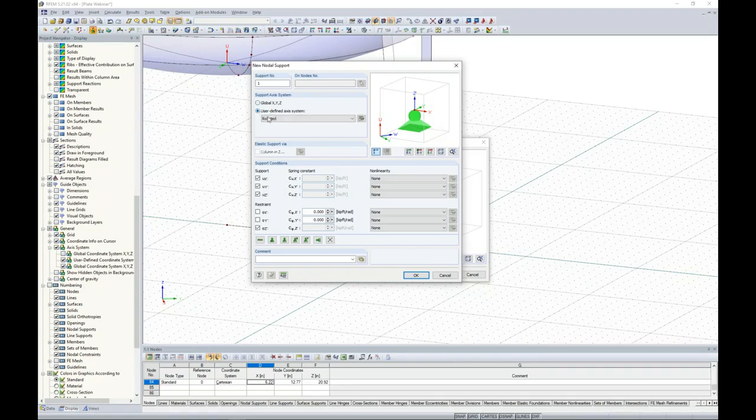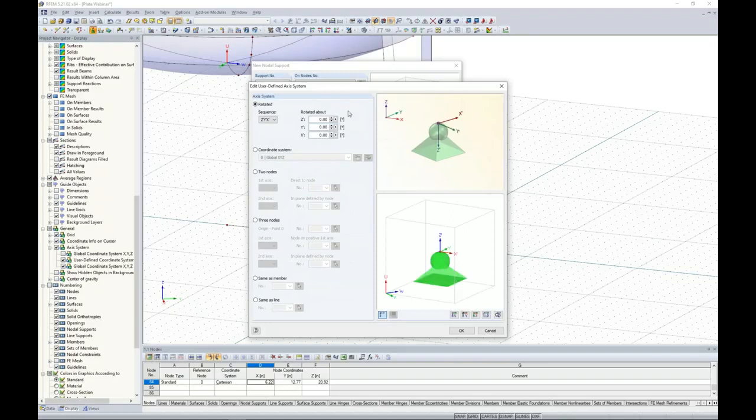So how do we slightly rotate this support? Well, we can use this option here to rotate the axis system. I go under my detail settings here, and I can specify the specific angle about the X, Y, and Z axis I'd like to rotate, but better yet, we have the ability down here at the bottom to reference another object in the model. And for this example today, I can graphically select this line. If you remember, we created it a little while ago, line number 49.